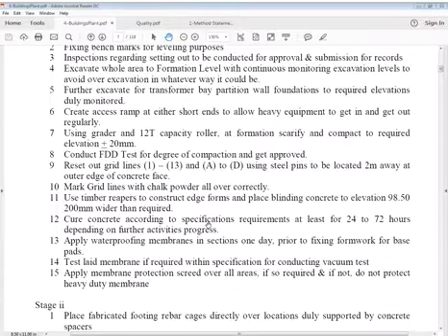Well, it is practically what you do. Level difference is always there. So you have to scarify, you know what is scarifying, just giving some cuts in that compacted earth so that it's well suited, dense one. And of course you take test of that, that's called conduct FDD, that's called field dry density test for degree of compaction and get approved. Of course, approval is a part of the process, it's quality control process.